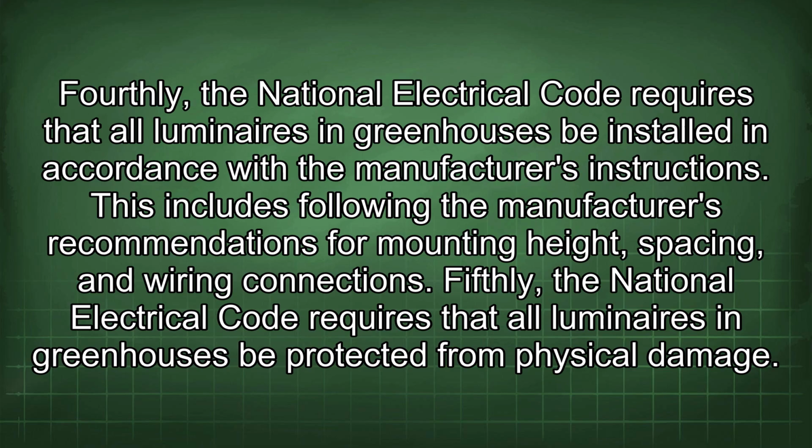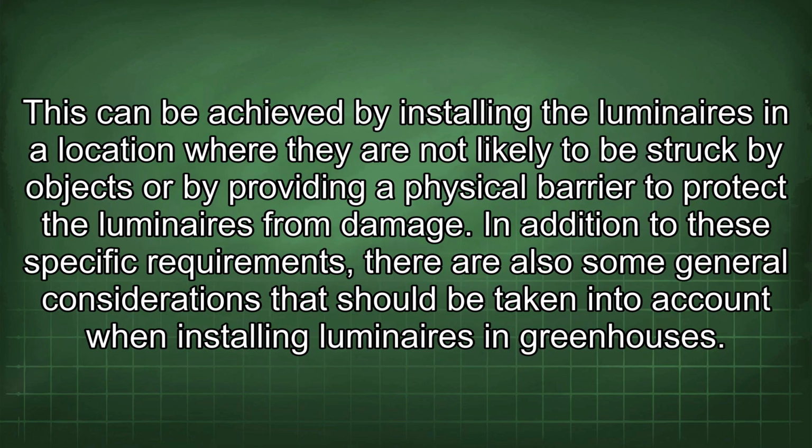Fifthly, the National Electrical Code requires that all luminaires in greenhouses be protected from physical damage. This can be achieved by installing the luminaires in a location where they are not likely to be struck by objects or by providing a physical barrier to protect the luminaires from damage.